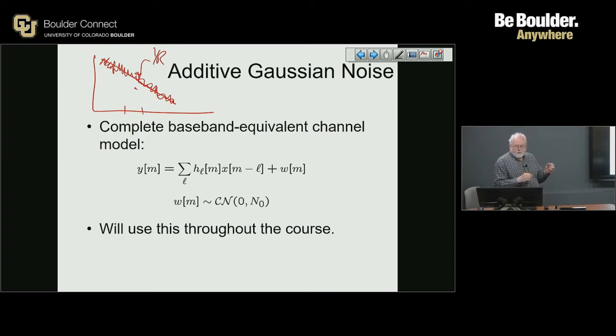So if I put an access point on that wall over there and then took a receiver and just started walking straight away from it, I would get something that looks kind of like this. It would actually be steeper than 1 over r squared, but there'd be all this variation from measurement to measurement because I'm going through multipath fades. The way we typically accommodate that in the path loss equation, and we'll spend more time talking about this, is that you can apply a standard deviation. You can look at the standard deviation of the observations at a given range. So the path loss will be a certain number of dB plus or minus a few dB at a given distance from the access point.